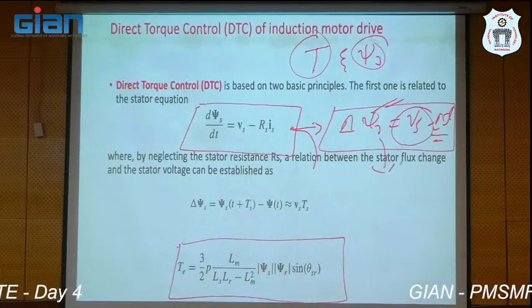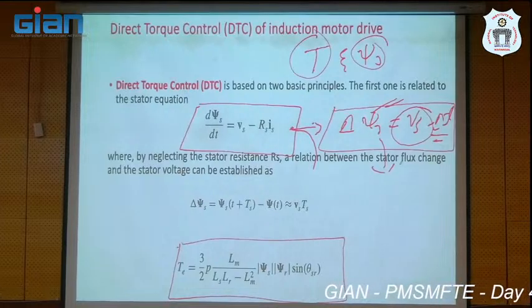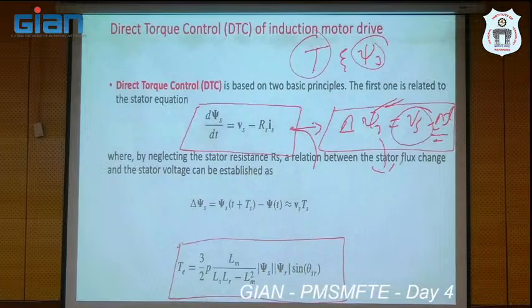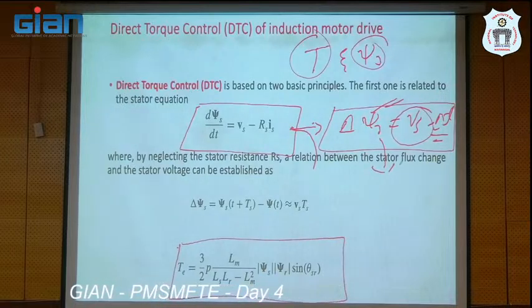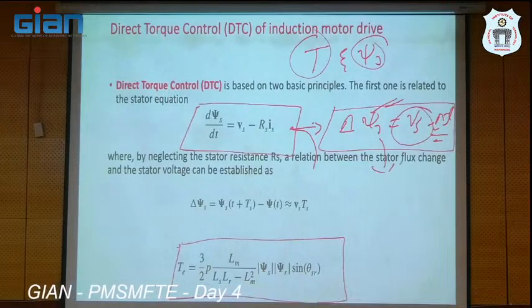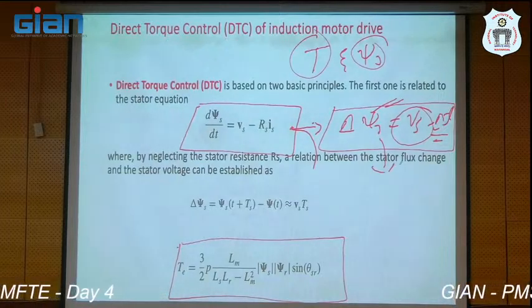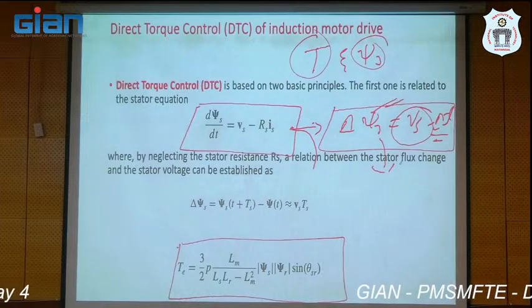But the reaction torque problem is that if there is any problem with the strength of the magnetic poles, for example permanent magnet pole strength, because of the heating effect it may lose its strength. Once the permanent magnet strength is lost, in a surface PMSM machine, what will happen? The torque generated by the machine will come down. But reluctance torque is always independent of the strength of the magnetizing poles, right?